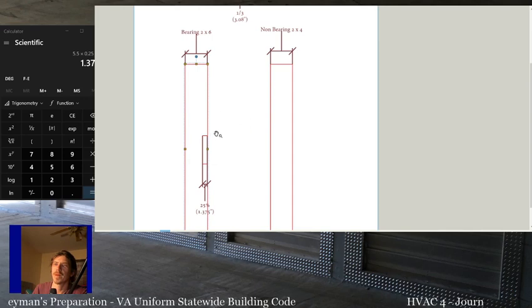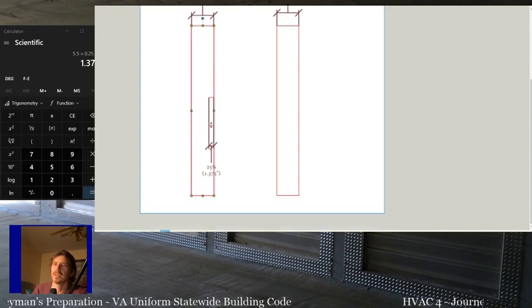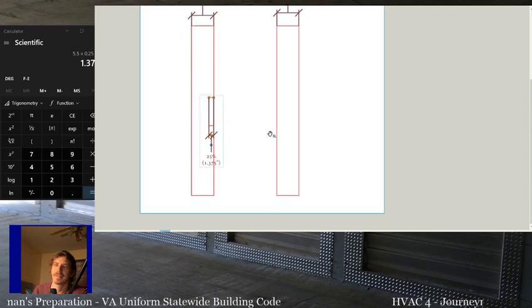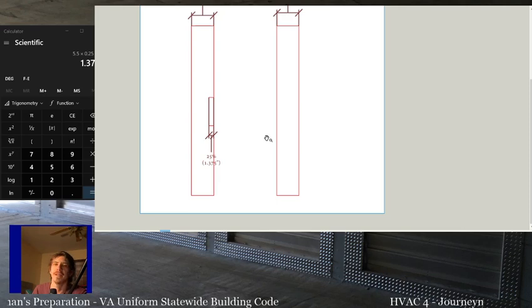All right. So 25% of a notch of the depth. It can really be as long as you want it to be. It can be almost all the way down the wall by code. It's not a great idea, and the inspector might have some questions or want a steel plate to go down it, but there's technically no maximum length. It's just depth. Okay.